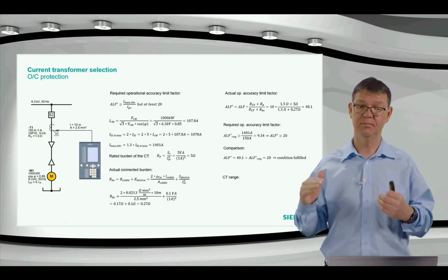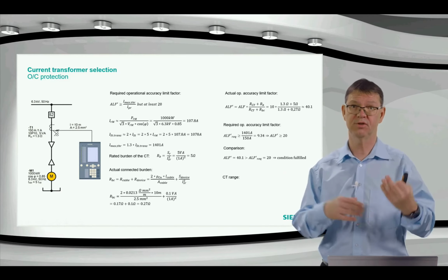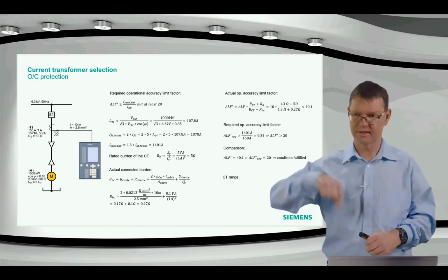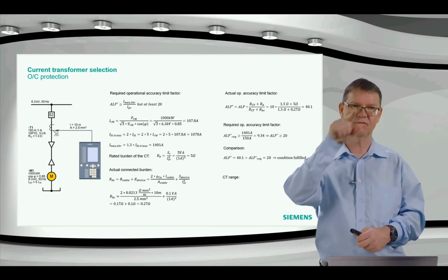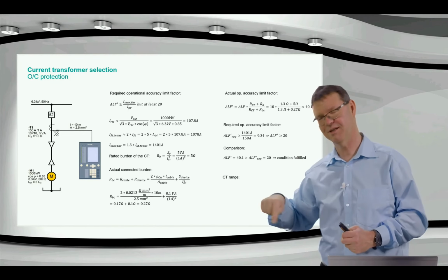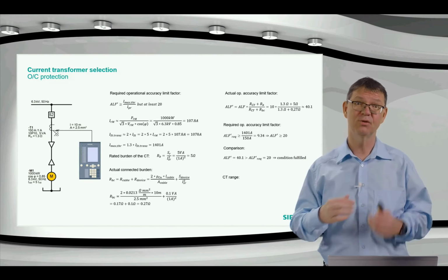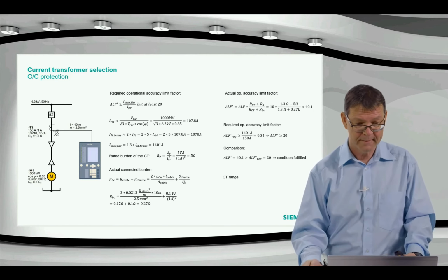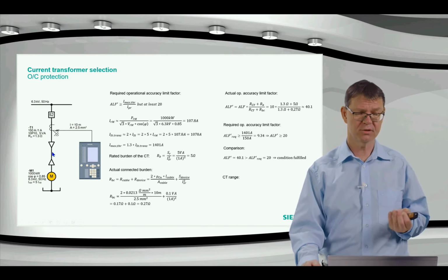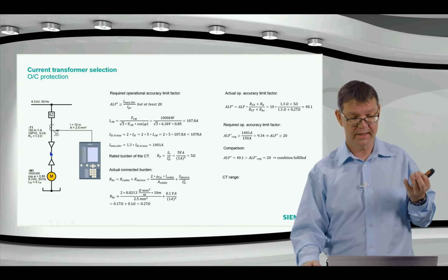Or is there kind of clipping? Because if the secondary current is bigger than my measurement range, I will have a clipping. So then I see a sine curve, for example, but instead of having the tip, I see a part of the sine curve and then a flat part, and then it goes down because the ADC does not go further. To do that, we need to know what is the biggest short circuit current which I can get here.